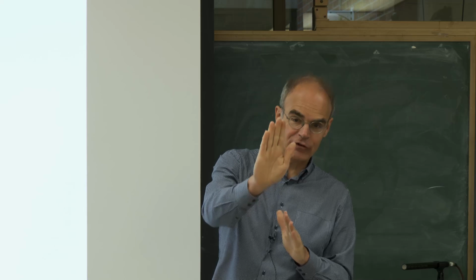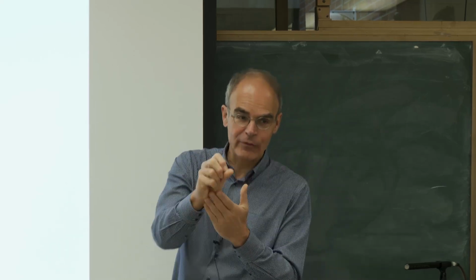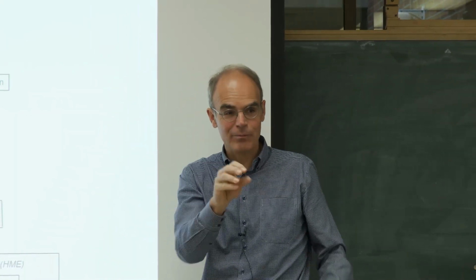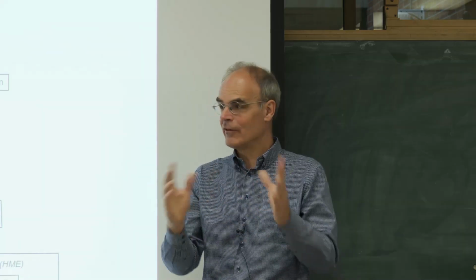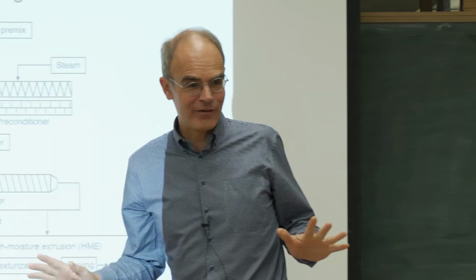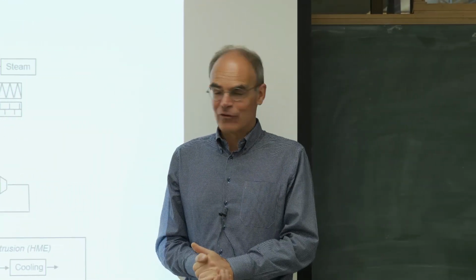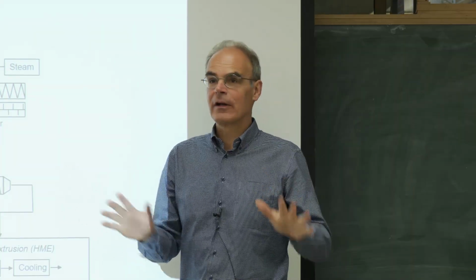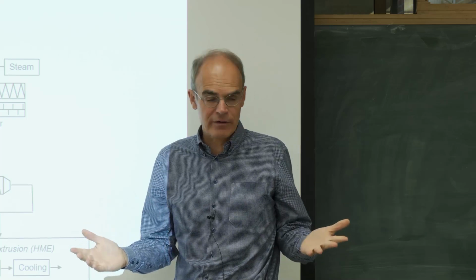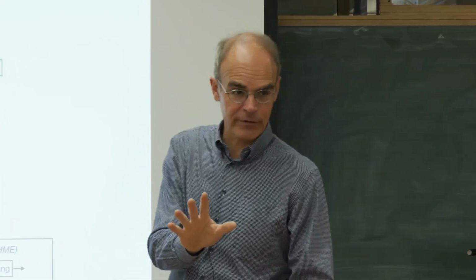But then you build up the pressure at the die because there the egg sets. And then you need to be able to push it, but with a very runny material, it's very difficult to get enough pressure to push that egg out of the die. So the die might block up with scrambled egg, which then gets overcooked. Then you can of course try to clean it a little bit, but that's the issue. So that's really the limit. But typically for any practical feasibility, I think 60-65%, maybe occasionally 70%, there you're going to stop, unless you have very unique ingredient properties.